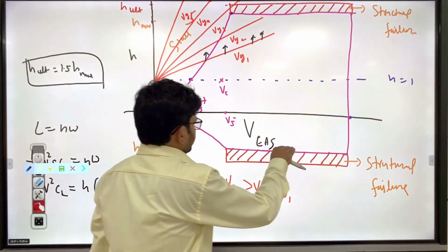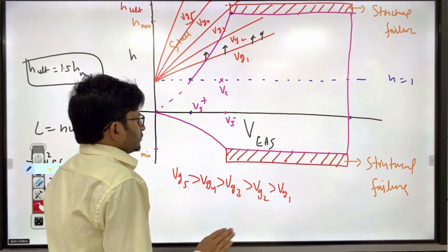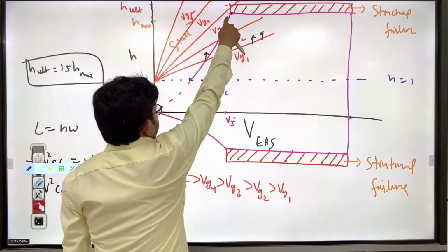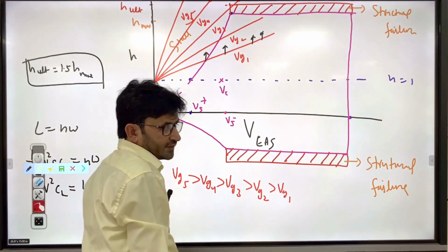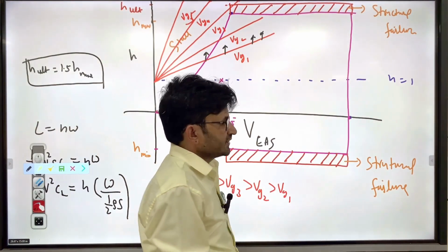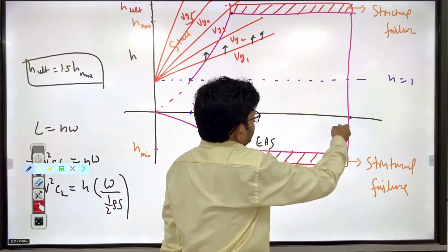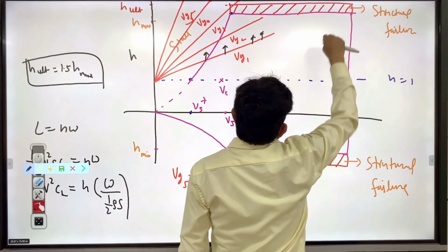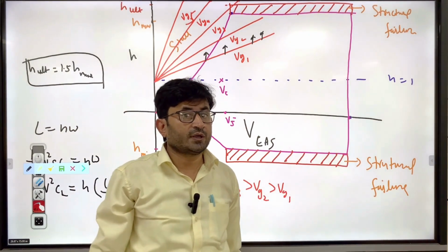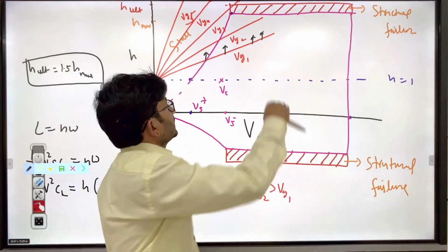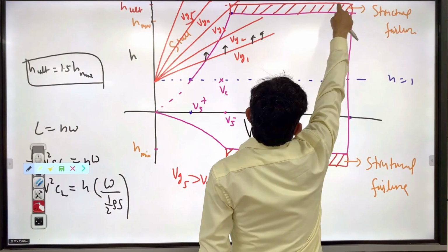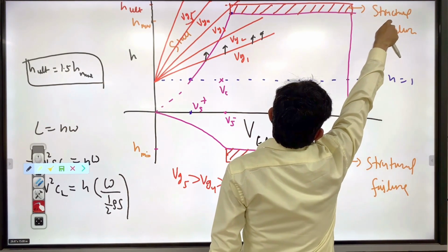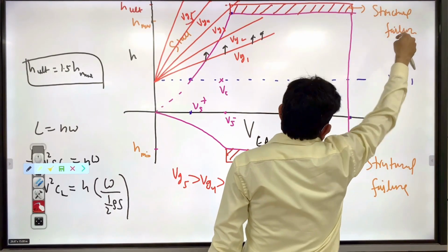Now, you take equivalent airspeed. First thing is to find out the stall speed. And then find out the corner speed, so that these 2 points you can locate. And based on the diving speed criteria or max speed criteria, you can draw this. And based on that maximum load factor, you can draw this line. Take an ultimate load factor 1.2, 1.5 times n max. Draw this line and mark this,